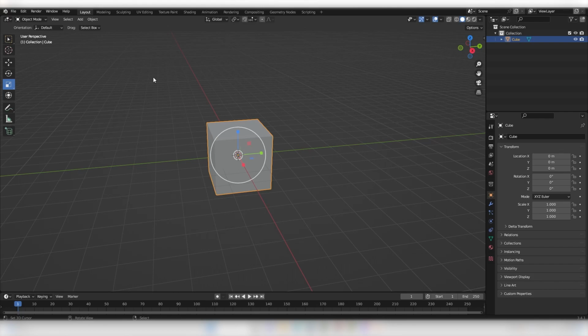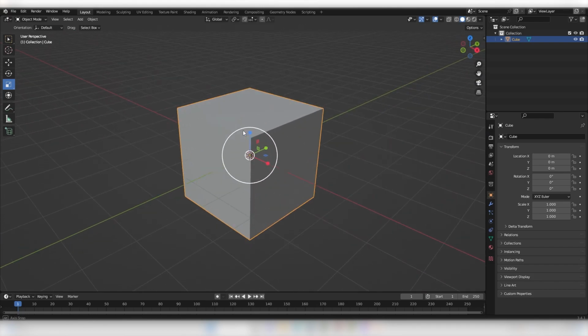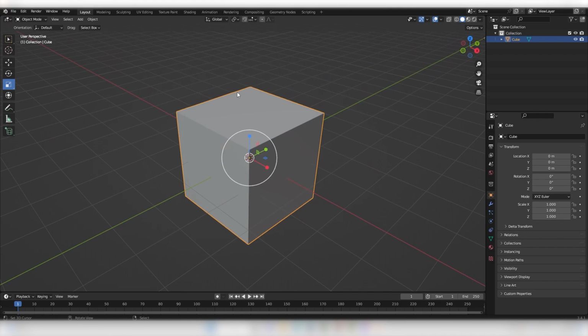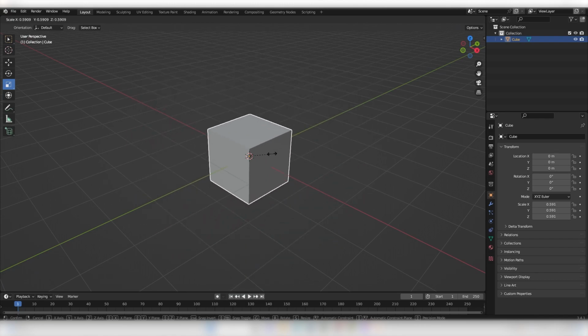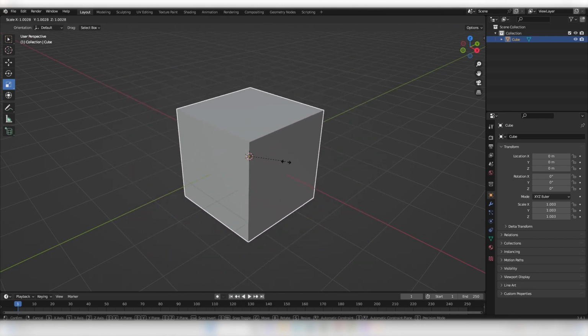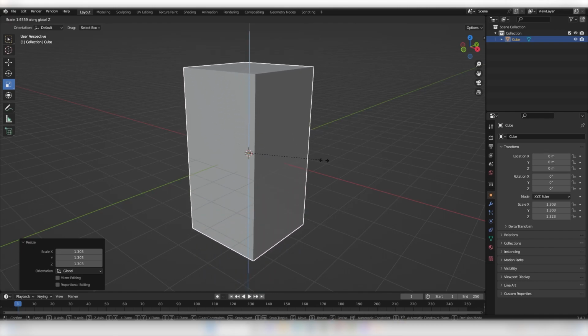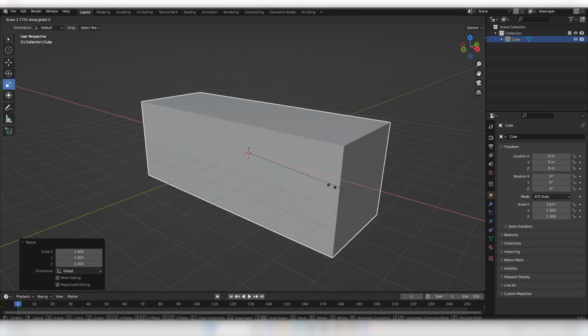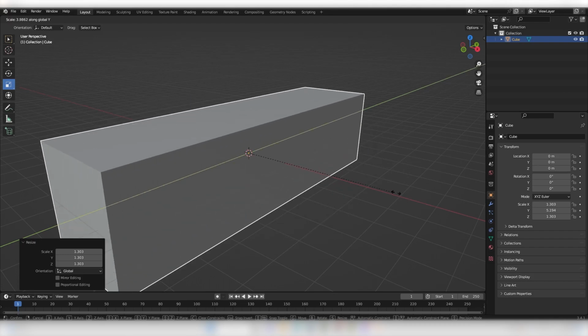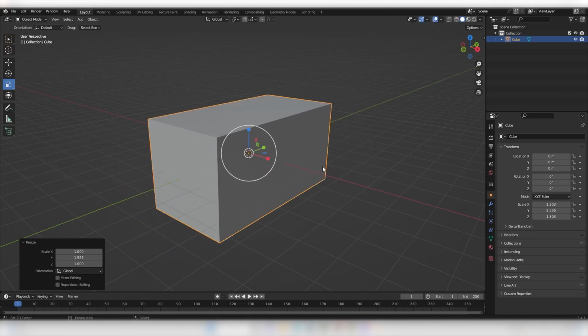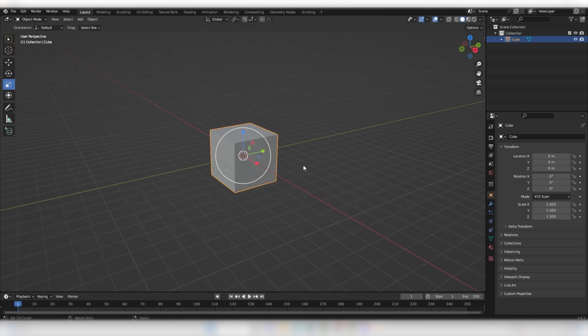However, again, a keyboard shortcut. Guess what it is in the comments? Guess what the keyboard shortcut for this is? Well, in fairness, the movement one being G is a bit random, but rotate is R, of course, and scale is S. So S will scale it just like this. It'll go bigger and smaller. But of course, you can do S and then Z to scale on that Z axis, S and then X to scale on that X axis, and then S and then Y to scale on that Y axis. It's all going to get very simple the more you model.